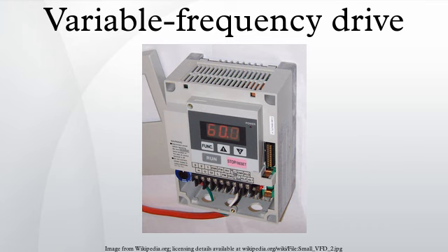An operator interface keypad and display unit is often provided on the front of the VFD controller as shown in the photograph above. The keypad display can often be cable connected and mounted a short distance from the VFD controller. Most are also provided with input and output terminals for connecting push buttons, switches and other operator interface devices or control signals. A serial communications port is also often available to allow the VFD to be configured, adjusted, monitored and controlled using a computer.